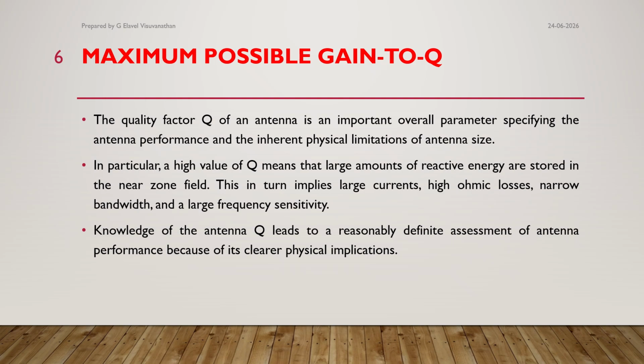So knowledge of the antenna Q leads to a reasonable, definite assessment of antenna performance because of its clear physical implication. So you should know about the Q factor, that is quality factor, which leads to a reasonable assessment of antenna performance because it clearly gives the physical implication.